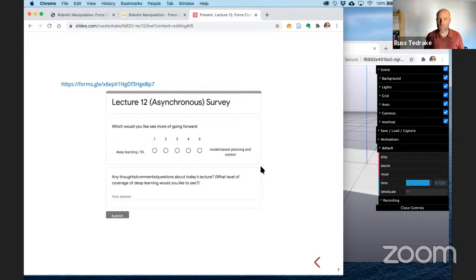Could I ask how much of the TRI book example was automated and how much was scripted? I mean, all the force control. So we basically consider on the KUKAs the threshold for how well you can measure force via the joint torque sensors. I'll tell you, it's 5 newtons. There's a threshold right around 5 newtons; below that threshold, it's going to look like noise. You shouldn't count on it. Above that threshold, you can do reasonable control.